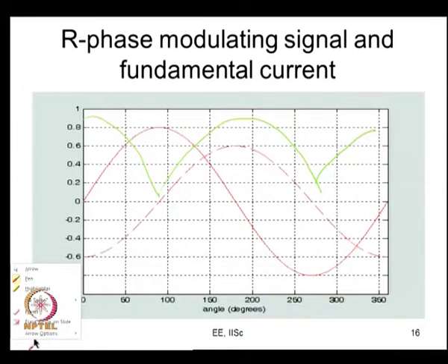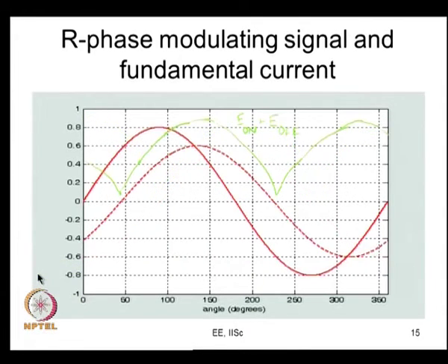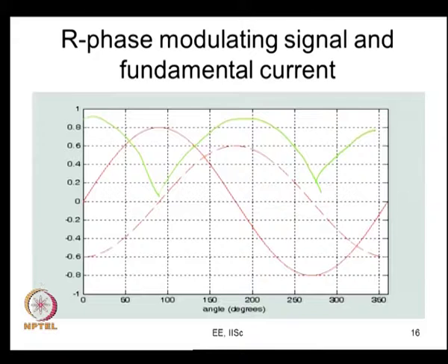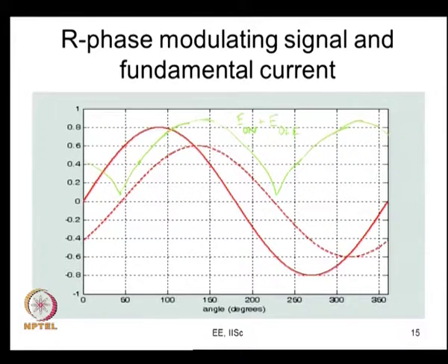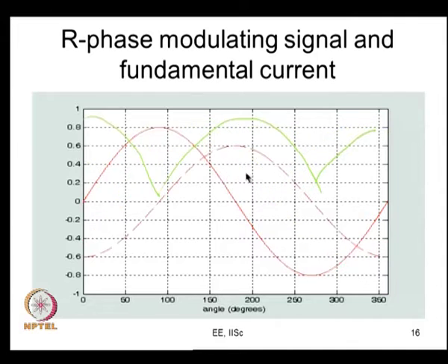If you look at the difference between here and the previous one, you look at this and that, there is no difference except a difference in phase. So, the variation of the switching energy loss is quite similar, and its average value will be equal. So, what does it mean? What is the difference between here and there? The load current is the same, but the power factor is different. So, even if the power factor changes, the switching loss does not change significantly.